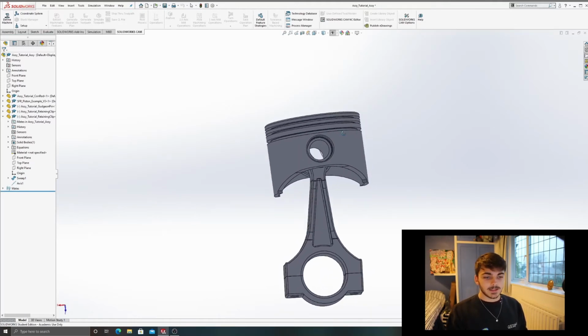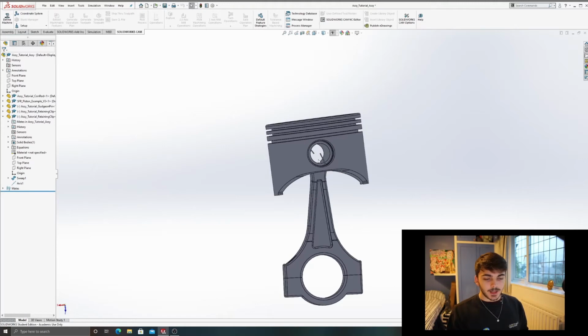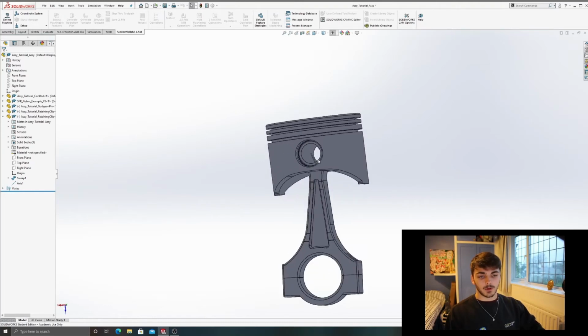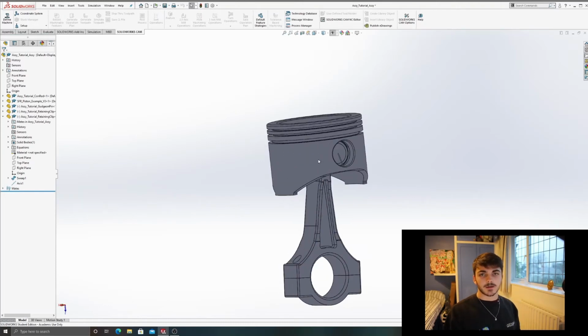That's really easy. The next way that you can rotate around is by using the arrow keys on the keyboard. The direction of the arrow that you press determines which direction you rotate in, and if I'm correct, it rotates you by about 15 degrees each time. So pressing the up arrow, rotating this way, down arrow, left arrow, right arrow. Really easy. Just a nice way to move yourself by a small increment without having to faff around if you're doing other things with the mouse.